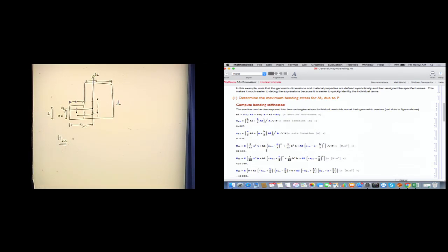Right? And if we are calculating H33, we take the distances which are parallel to I2. So H33 is the sectional bending stiffness about I3. So the distances that matter are perpendicular to I3. The distances which are parallel to I3 do not matter because they do not induce that stiffness.